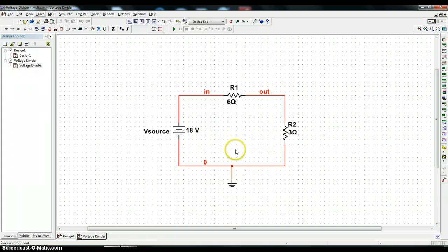What is often confusing to students when they learn about Thevenin's and Norton's theorem is to determine the equivalent resistance looking back into the circuit. Now, to do that, you de-energize any sources inside. If you had current sources, you would replace those by open circuits. Let me make a comment about how you de-energize a voltage source. On paper, or in this case on a computer screen, you would replace the voltage source by a short circuit for analysis purposes. You would never do this in a laboratory because in some cases it could even be dangerous to short a voltage source.